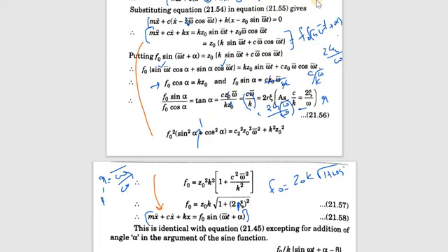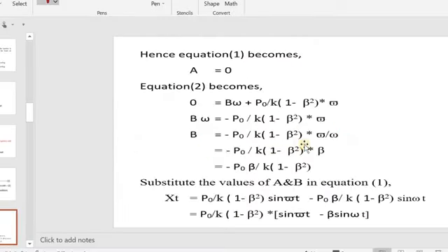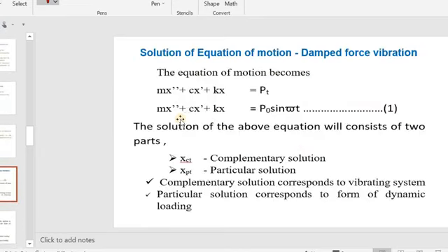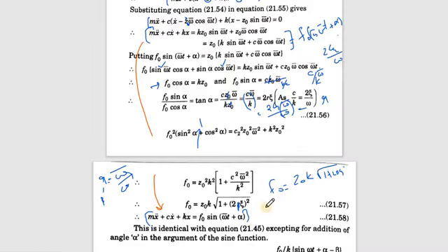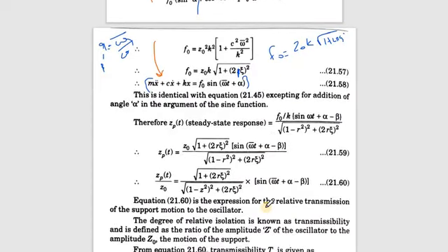So what has happened here is that a ground motion is being converted into a forced motion. This is a harmonic motion. This we studied in our harmonic loading video, which you can refer to. From here only it started, with this equation we have studied, m x double dot is equal to p0 sine omega t. It is the same equation. So we converted a ground motion to a forced motion. Then it will be easier for us to find out the values.